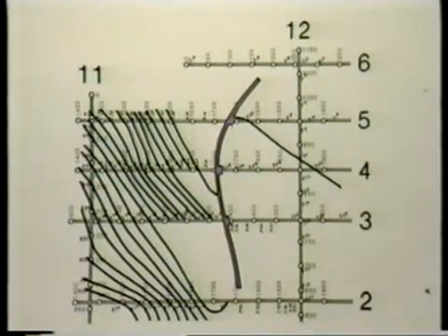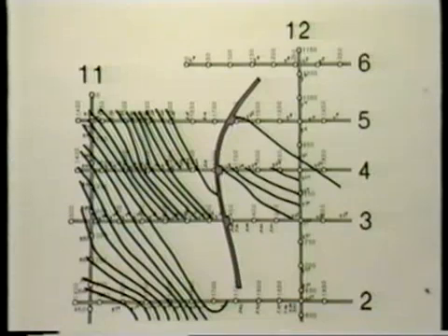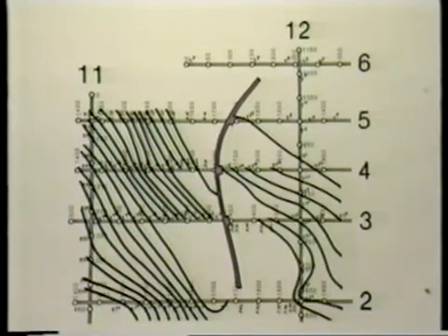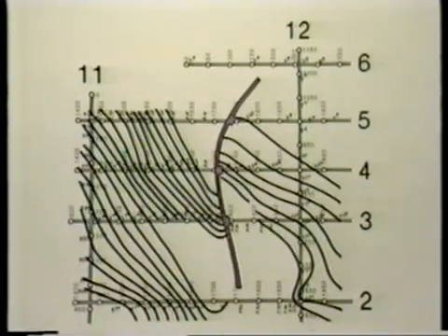Now we can add a few more simple ones. Mostly regional dip again, giving us the general direction of the contours. Then, with some care, we project the remaining contours up to the fault. Each contour which enters the fault must also leave it. Somewhere in here we must add that antithetic fault down to the west, and probably a second minor one.